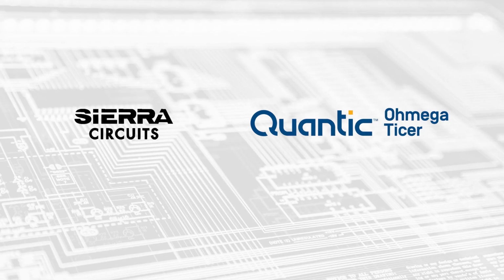So, how to design for embedded components in the PCB design, the tools. When it comes to embedded resistors, I mentioned that you have to create that window layer. It's an extra layer of artwork, but it works in all the different design suites. So you could use Altium, Allegro, well, all the standard ones work. It's just learning how to use it properly to add that additional layer. So it's really not a big deal. And the circuit board shops are really proficient in helping do that, and we can help as well.